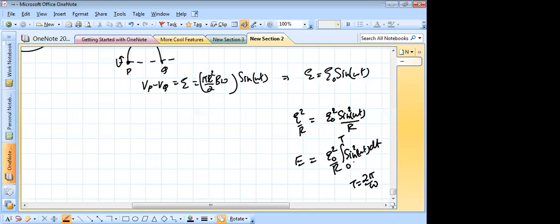Basically, you can use that trick also, that RMS value of sine square is 1 by root 2. So the average value of sine square is half. So this integration will actually be capital T by 2. The value of this whole integration will be capital T by 2, because the average value of sine square is half.